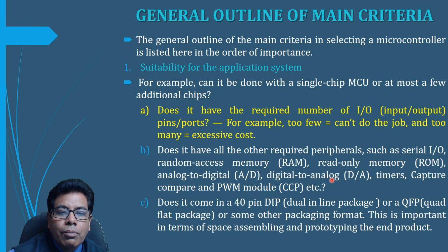Apart from that, we'll have to see whether the different pins, peripherals, communication interfaces, and package are suitable for the application or not. So does it have the required number of IO pins or ports?